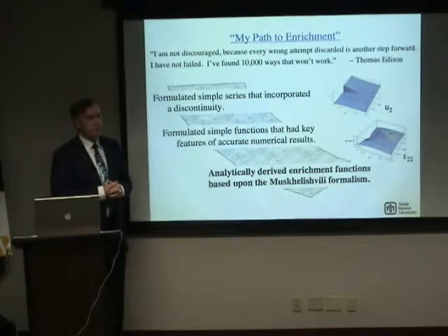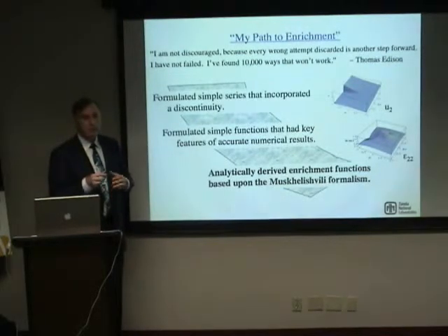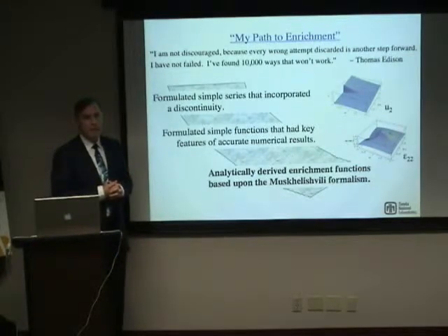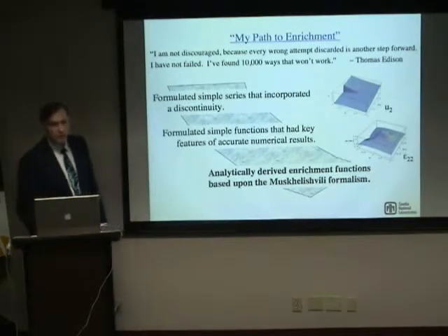I maybe shouldn't even use the term length scale, but there's a length parameter associated with the solution, which is the length of the cohesive zone. Yet that's something we don't really know ahead of time. That's a function of the boundary value problem. And as such, it would make sense that the region that we're going to enrich is actually tied to that length. And so I'll mention neighborhood enrichment in a minute in terms of determining how to enrich.